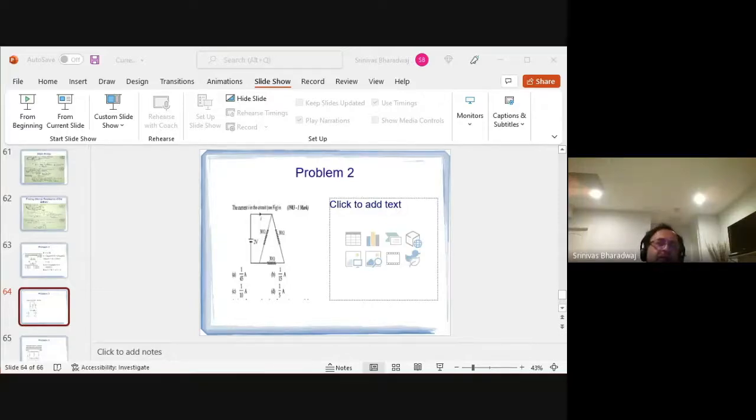Okay, now these two are in series. So 30 plus 30 is 60. So you have a 30 plus a 60 in parallel. What is the effective resistance? 60 times 30 divided by 60 plus 30, which is 60 by 3, 20.